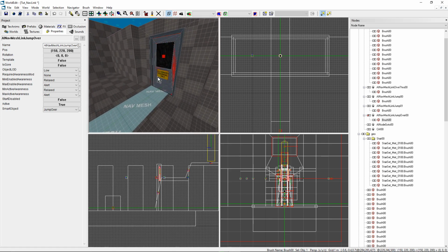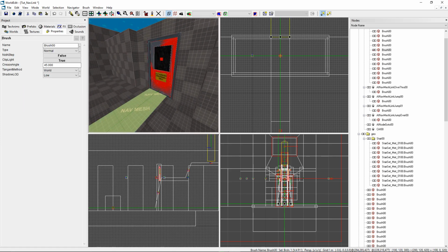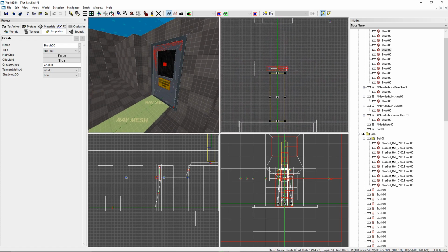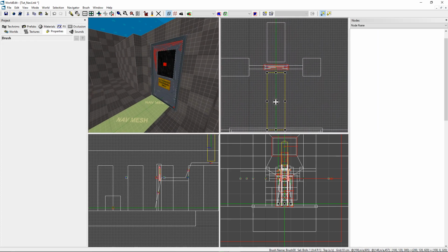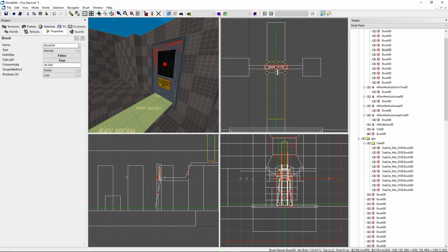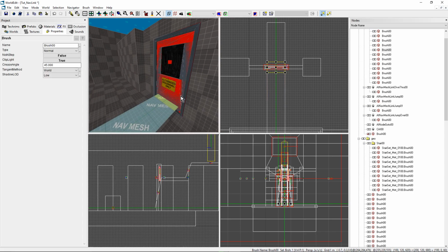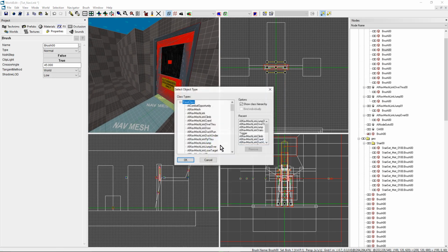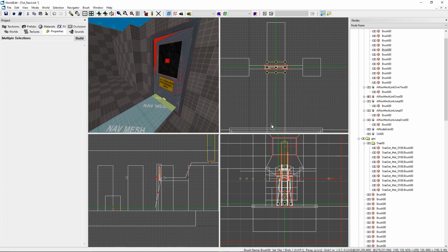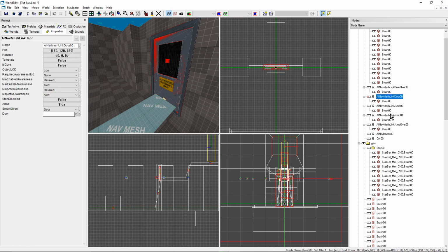Next thing, we have a door. For a door, let's create the link first, like that, then center marker, and again bind to object, but choose this time a Navmesh Link, a door. And if I select only the door, like that, Shift to select only.